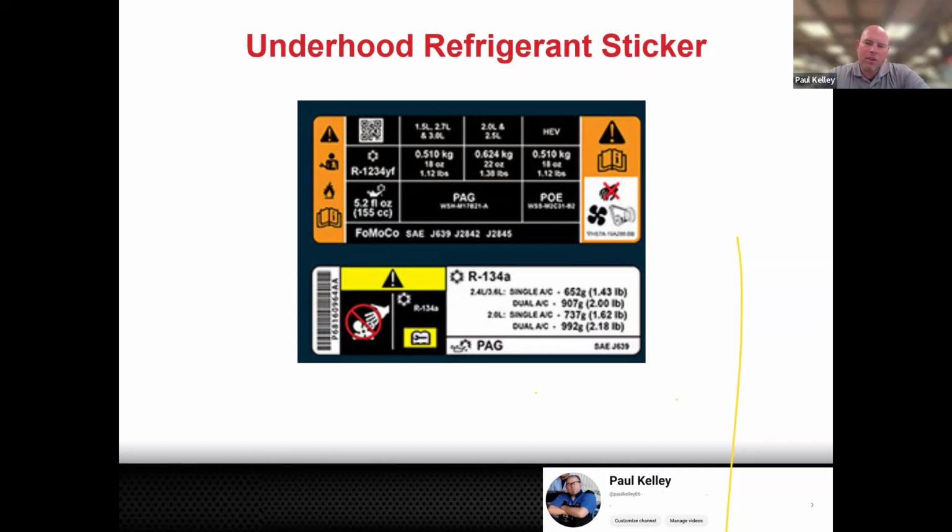You can't have highly conductive oil inside there because there are windings in the compressor, and you may get a phase to phase, almost kind of like a short. You may also get high voltage to the ground, to the housing, which is grounded because it bolts to the block.